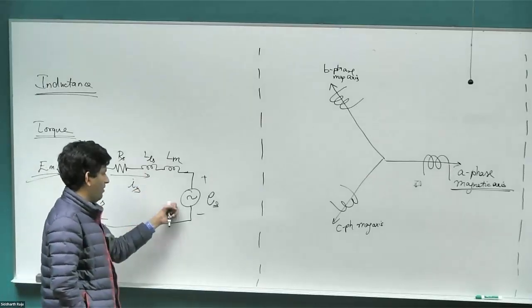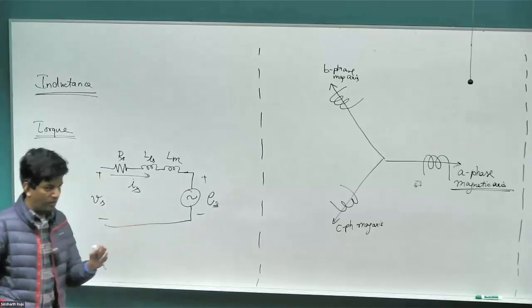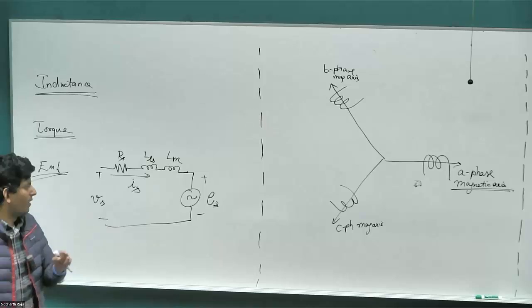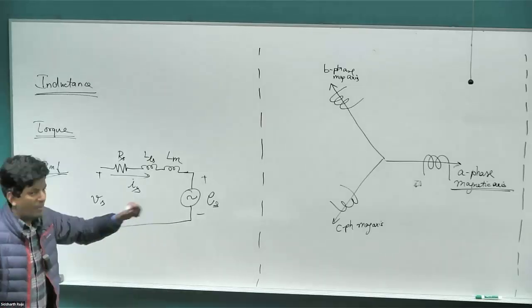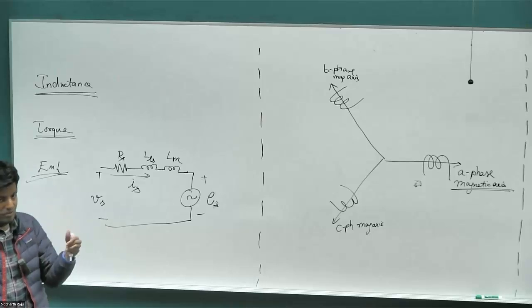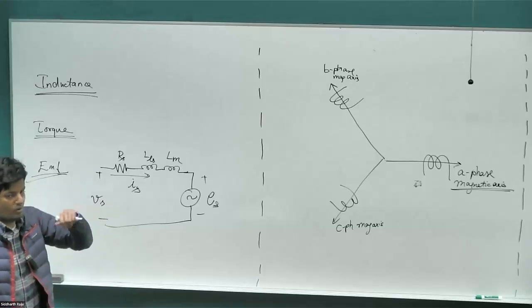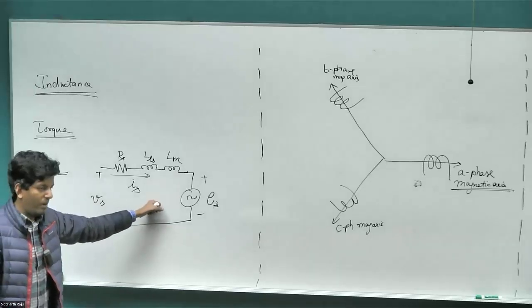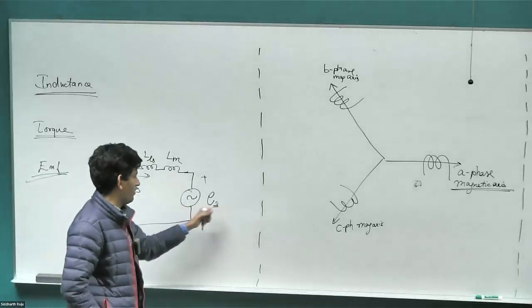Right, and then finally, we so far haven't introduced the rotor yet. All we have done is analyze the stator part alone and the sinusoidally distributed winding of the stator. But the minute you put a rotor in, and the rotor starts to rotate, it is going to have its own magnetic field because the rotor is a magnet. And when the rotor rotates, it's going to have a magnetic field that's changing, which means the flux is changing. So there's going to be an EMF induced across the stator winding, which is experiencing this change in flux due to the rotating rotor magnet, right? And that EMF we are going to indicate as ES.